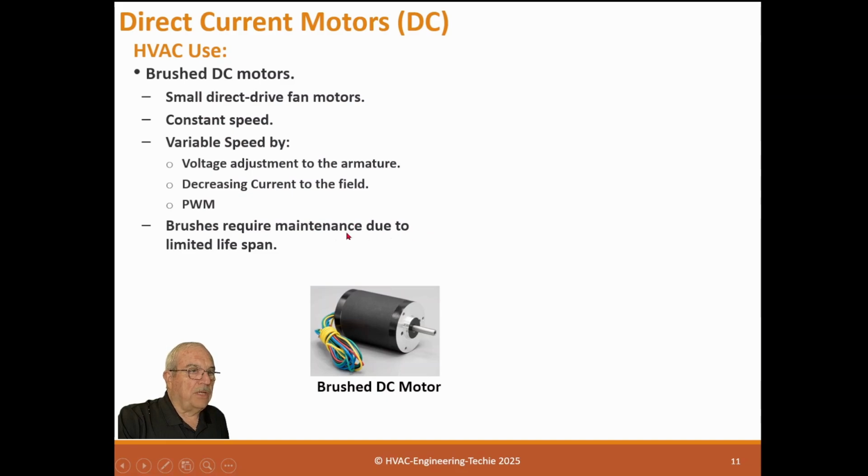It requires brush maintenance due to limited lifespan. The brushes are just carbon pressing against an armature on the shaft, and they will wear down over time. All the drill motors used to have brushes. Now they're brushless, but they used to be that way.